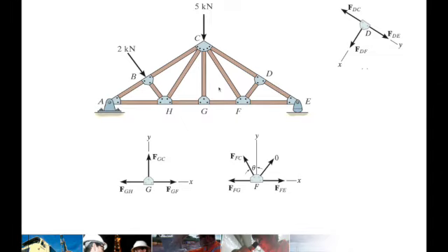So are there still others? No. So what we have is this joint, this member, and this other member are all zero force members. But please, in your design, as you are architects, please don't remove this. Don't remove these members. Okay, so that is for zero force members.